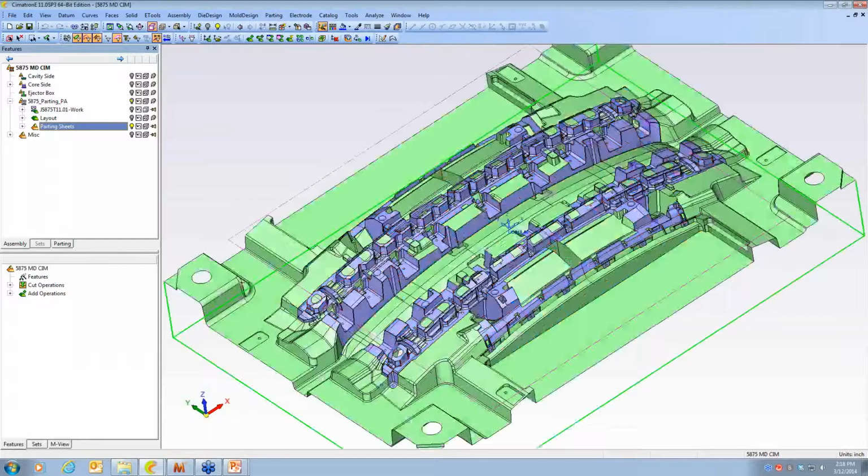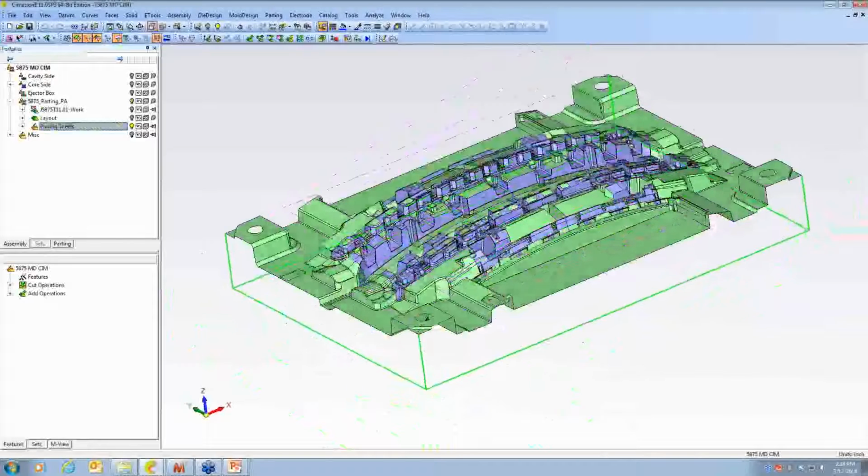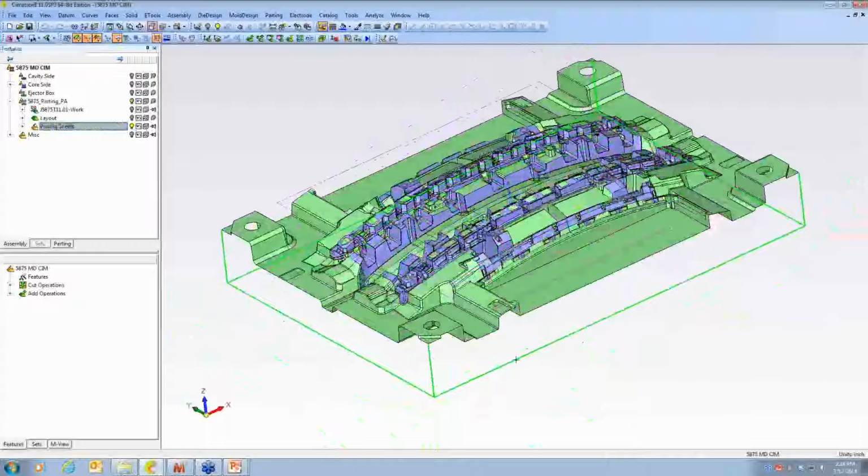So in this example, the core block is nearly 6 feet long, and designing a cooling system of long winding circuits isn't really an effective way to pull the heat out of so much plastic. The distances are too great, and the cooling effectiveness of the water is going to decline. So instead, molds of this type are usually designed with straight-through channels interrupted by baffles that direct the water up near the part surfaces.